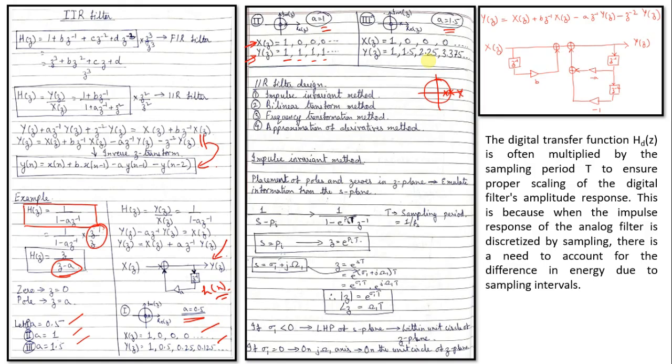Now since it continues up to infinity, what happens? The coefficients are neither going out of bound nor dying down. Due to this reason, this filter would be regarded as neither stable nor unstable, or we can say a marginally stable filter.